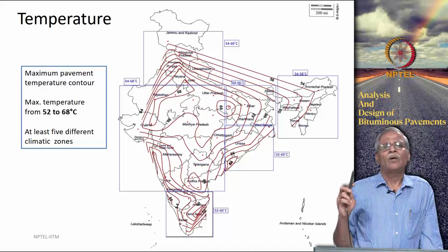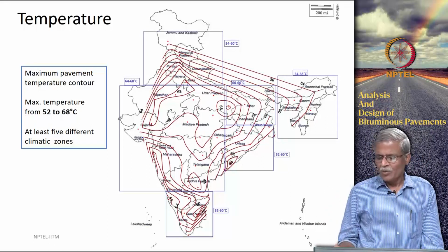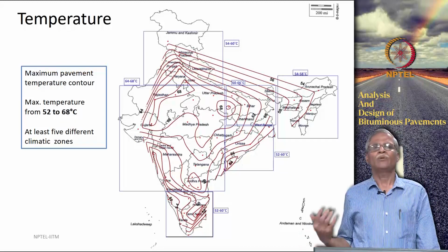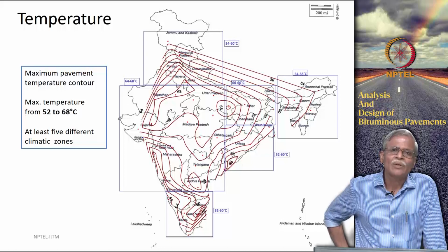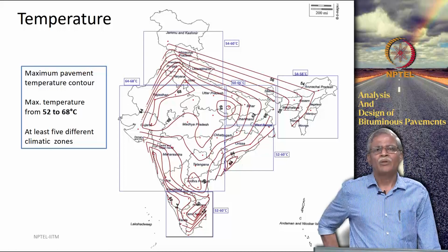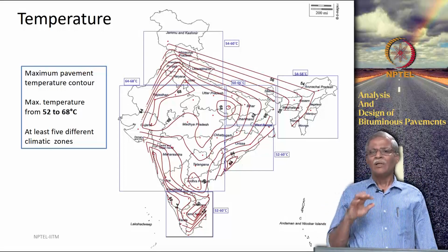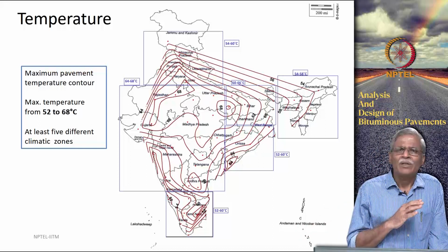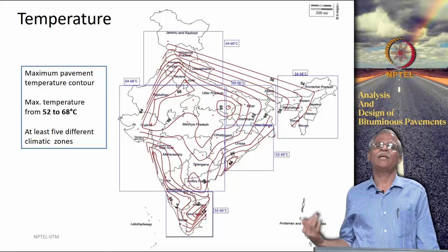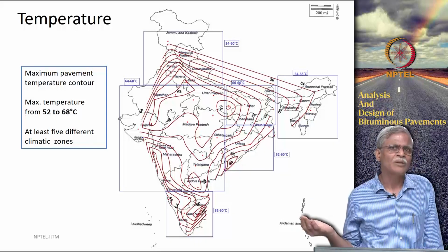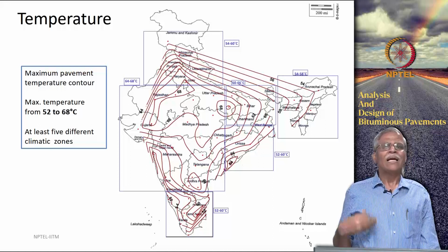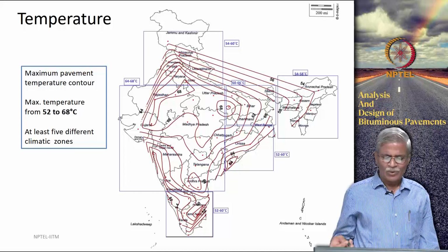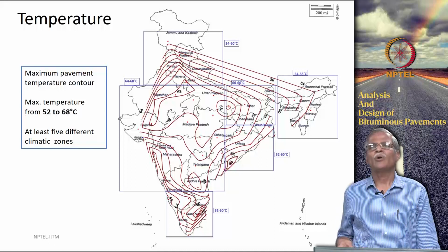Now, coming back to whatever I was saying, what Dr. Nivita did was to collect this data and clean up the data. So, we collected around 40 years of air temperature data from the meteorological department Pune and then cleaned up the data. There were many places where there were gaps. After cleaning it up, using established air temperature, pavement temperature models, she generated the actual pavement contour for the first time in the country, and you can actually see this is your pavement contour that you see here.